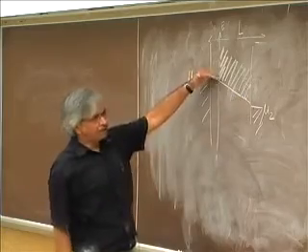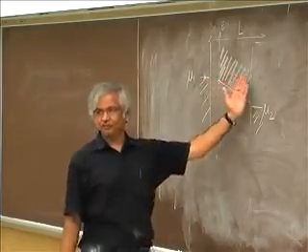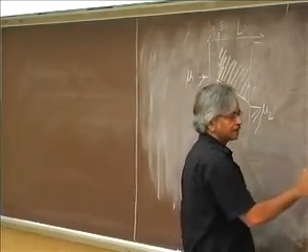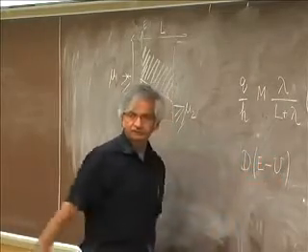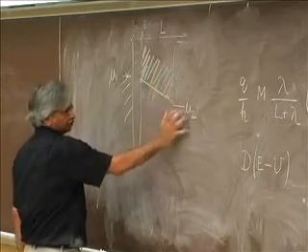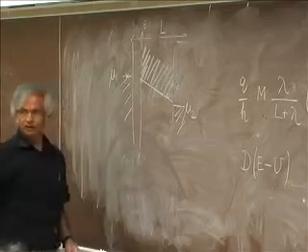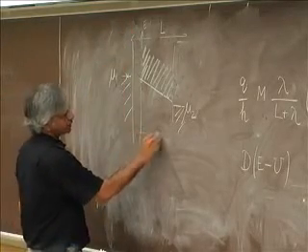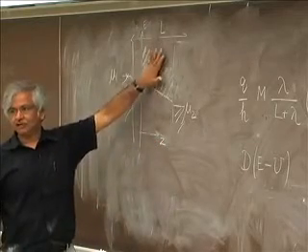So, as I said, when you have an electric field, the electrostatic potential is different. And because of the electrostatic potential, as I mentioned, the density of states should change this way, E minus U. If the electrostatic potential here is lower because you have a positive voltage, the entire density of states should go down. So what I'm trying to plot here is this axis is energy, this axis is Z, and I'm trying to show where the density of states are.